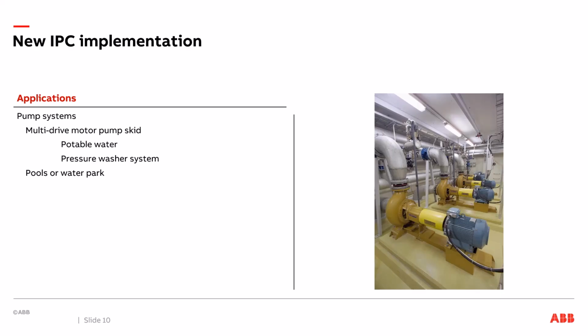The great benefit of this feature is, for example, let's say I know at a water park slides, I just need to run the drives at 40 hertz. Maybe it's even programmed in the drive at a fixed speed, preset in the drive. But I do have redundancy automatically in the water park, but the drives aren't tied together. There's no control system.